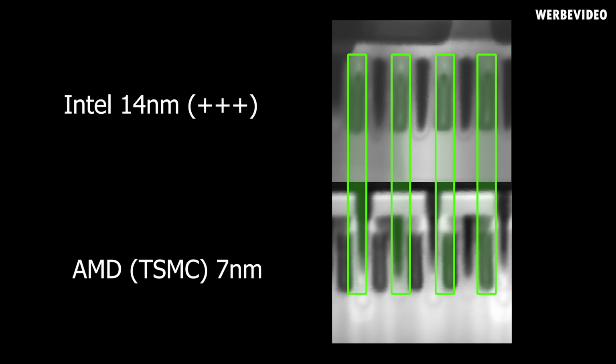You might now say or think, hey, who of them is lying to us? Like, why is an AMD 7nm CPU not half the size of a 14nm Intel CPU? And all I can say is it's not that simple. We have a FinFET transistor, which is a 3D structure, and obviously a 3D structure has more than just one dimension and one parameter. And judging a transistor or a structure by one number is stupid. It's as stupid as what we just did. We just measured one gate length and compared it for a 3D structure, and that just doesn't make sense.